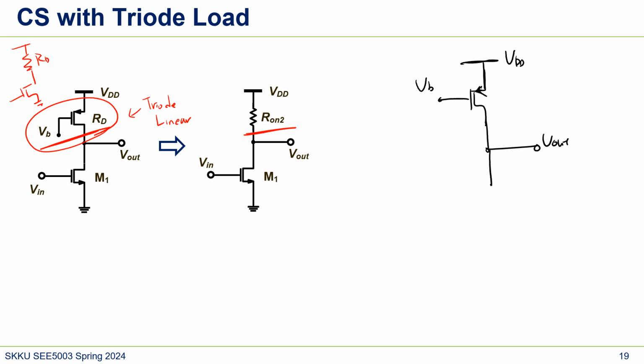So we want to make this in triode region. So what should the voltage Vout be? Assuming that VTH-P, and this is usually minus, right? Assume that this is 0.8 volt. And assuming that VDD is maybe 1.8 volts, can you tell what the level of Vout should be?